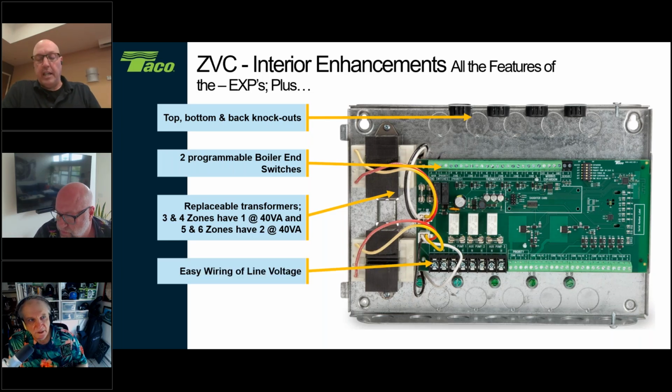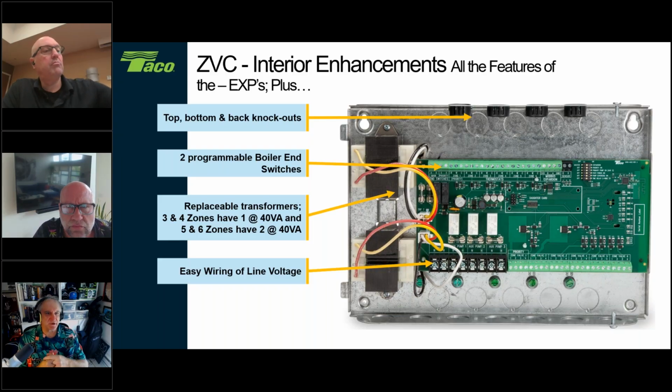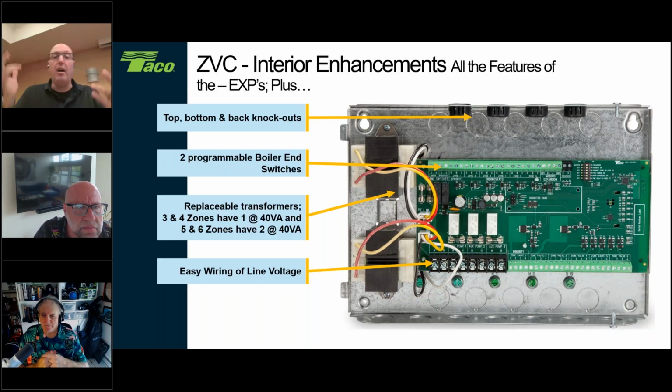Hey, Dave. Yes. Real quick question from Steve. Can we use any 40 VA transformer in a pinch as a replacement? I would say yes and no, because the transformers that we have here have the plug already on there. So you'll have to cut the plug off of it and do some of your own custom wiring. Make sure you follow color codes. And that's about it.